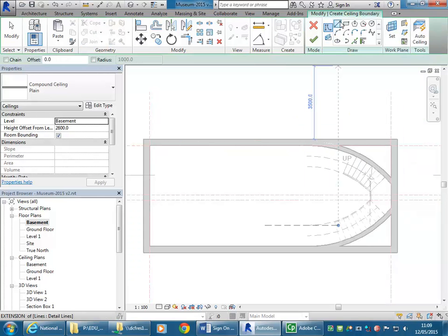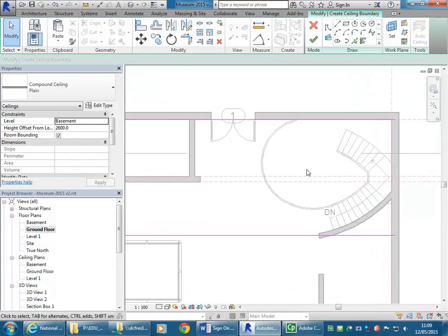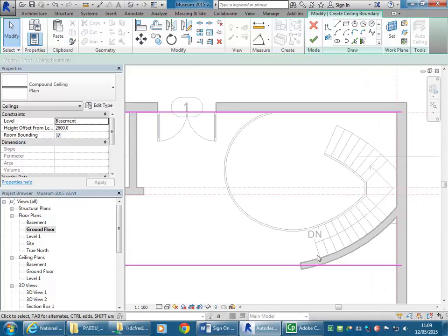And with sketch ceiling, it's like making a floor. You need to create the shape first in plan, and pick walls there can be a good option. So with pick walls, you can choose the inside face of any wall. Notice I've left the walls on the right because I know that I have a floor here that finishes along this edge. So I'm going to go and have a look in my ground floor plan, and I can see then the floor where the ceiling should finish.